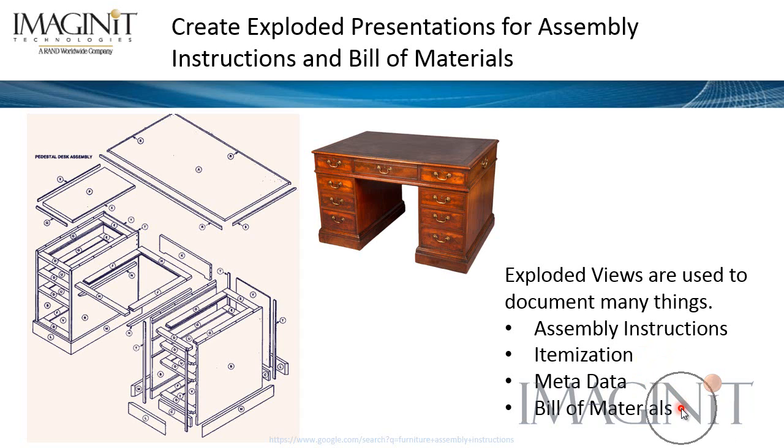A lot of times you go to the assembly instructions to find an item number, and then you go to the bill of material or to the parts list to find out the necessary information about that part. For instance, maybe the dimensions are recorded for this piece of wood. Maybe the material is included, or the thickness of the material. That information is not necessarily on the drawing view, but via the itemization bubble, you'll find it in the parts list.